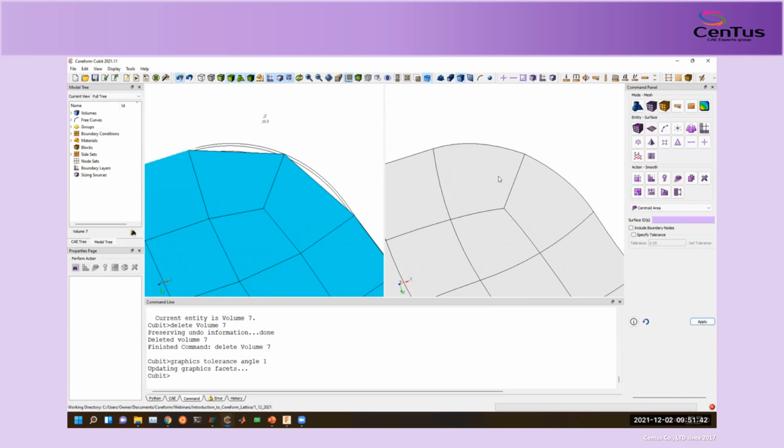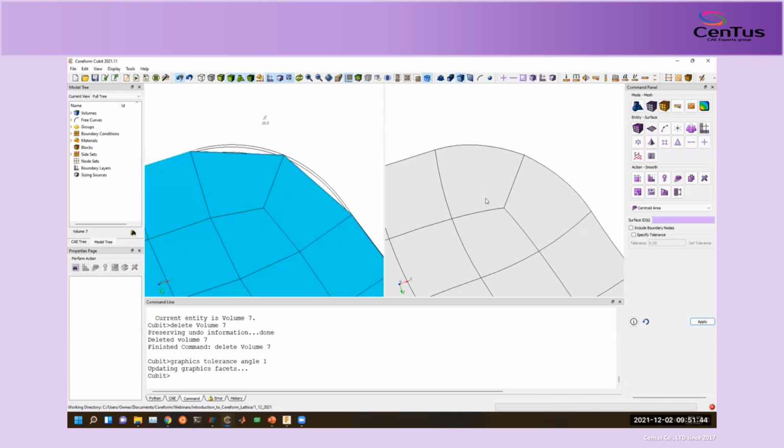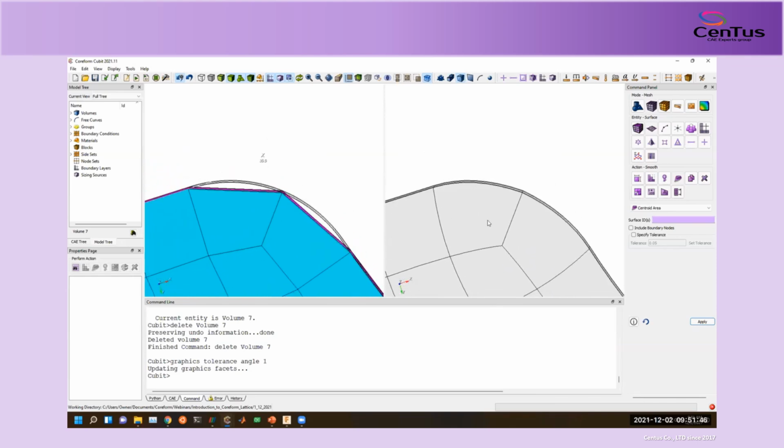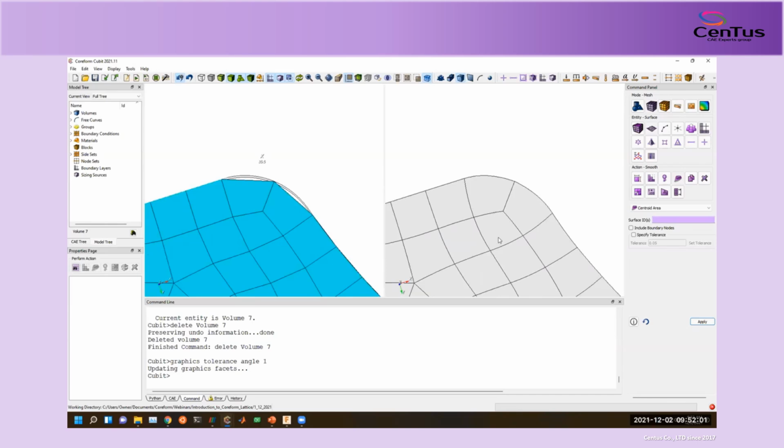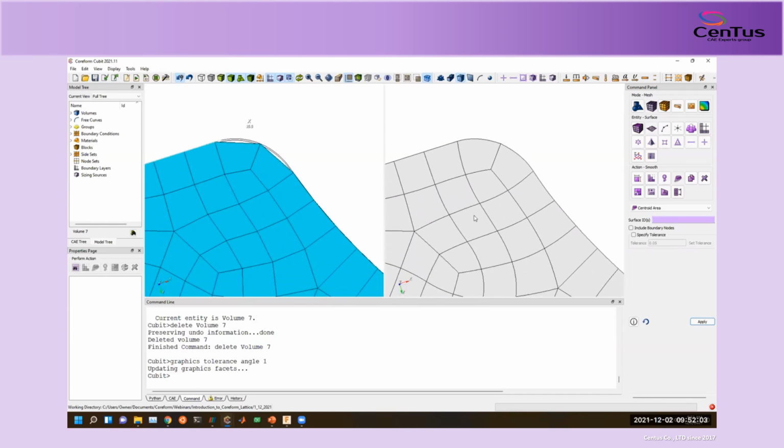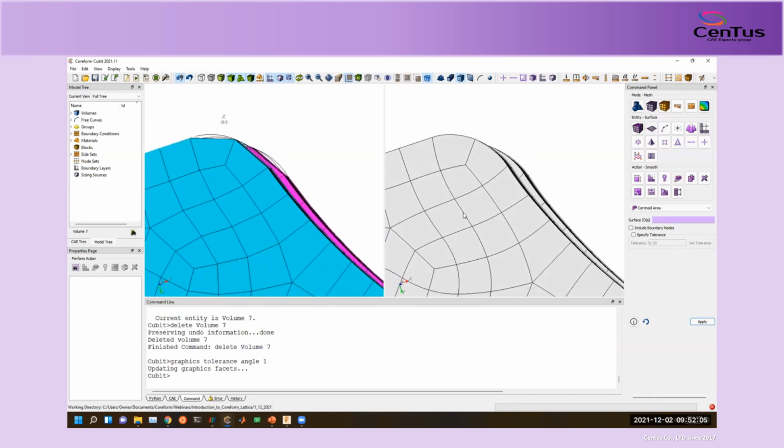Right now, we use a technique called Bezier projection with our U-splines. We aren't building rational U-splines yet, and so these are technically just an approximation to the original CAD geometry because they're polynomial as opposed to rational, for these cylindrical faces. We are working on rational U-splines as well. But they are a better fit.